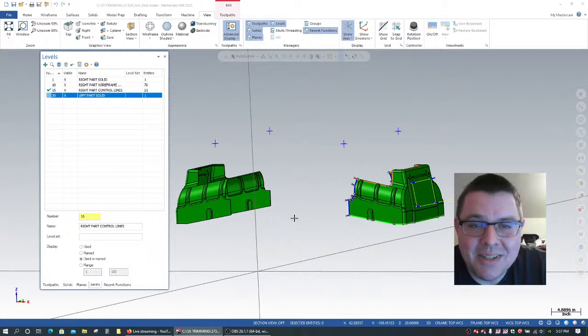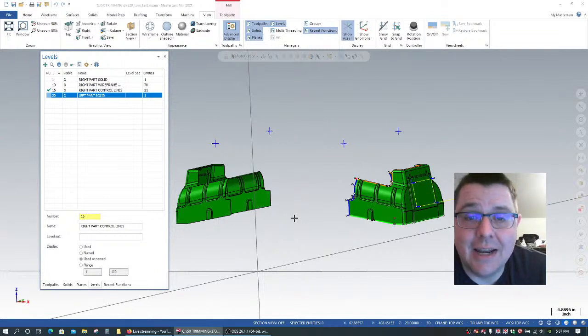what you've got in your file, and when you get to your NC code, where a certain section of NC code is being generated, if you put in a comment, it's a lot easier to tie it back to the specific spot within the Mastercam file that actually generated that NC output. So it's just a good practice to do that.